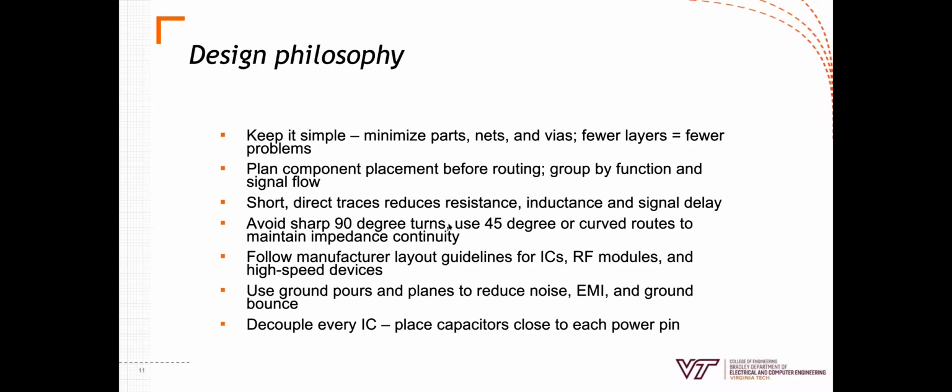Avoid sharp 90-degree turns, use 45-degree turns. This doesn't matter as much for low-frequency applications, but for high-frequency applications, these sharp 90-degree turns act like open connections, which is messy when you are doing high-frequency stuff because it basically makes an antenna, and you don't really want an antenna on your board if not necessary.